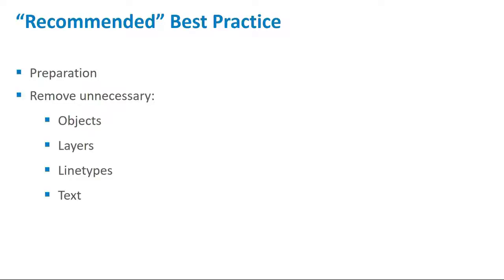I did see a couple of other questions. Yes? When you imported that 2D floor plan to construct a wireframe model, were you using the copy monitor function to make those grids? No, because you can't copy monitor a DWG. So all I did was I went through and used the pick line tool, and then just picked the grids, and the same with the levels as well.